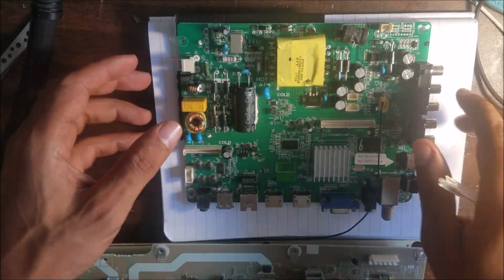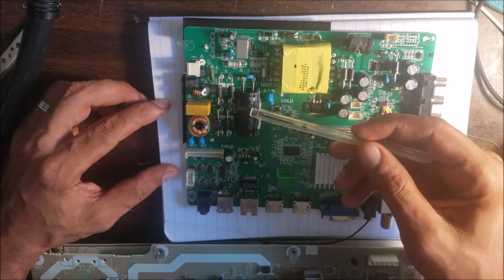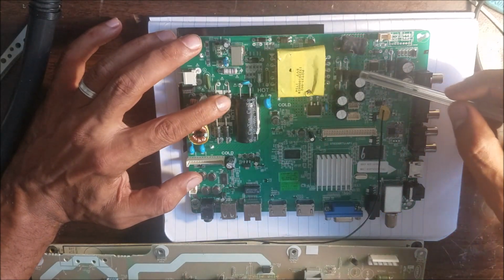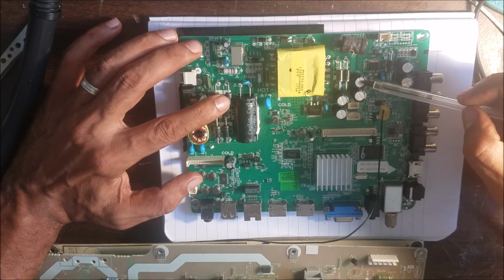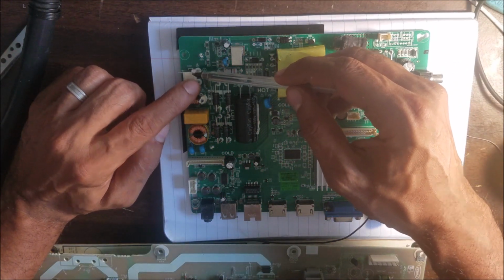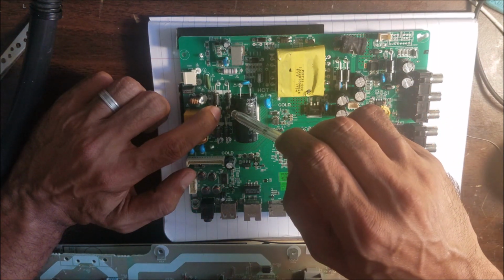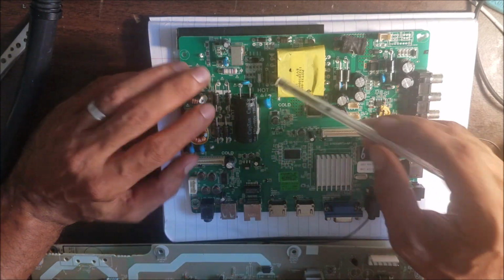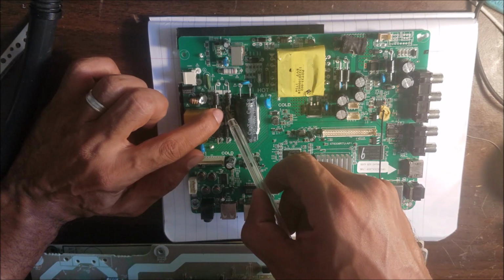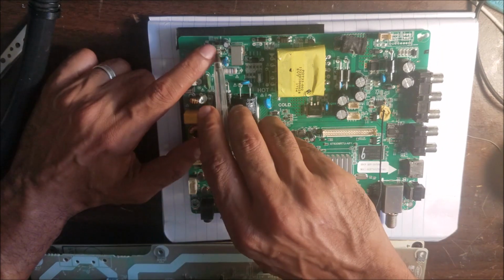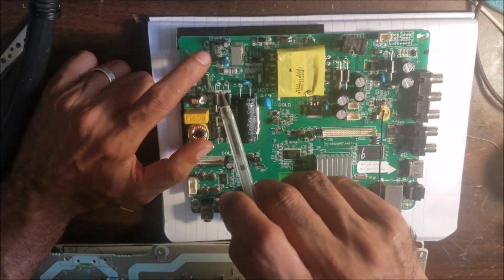This is the power supply that we find in any device, and these are our examples of power supplies. Here, in the switching power supply, we go from the rectifier bridge up to the output capacitor. If we take the power directly to the rectifier bridge, we don't use any of this, the power supply will work fine. So that's why I said we start from the rectifier bridge to the output capacitors. The basics, you're going to see in any switching power supply.